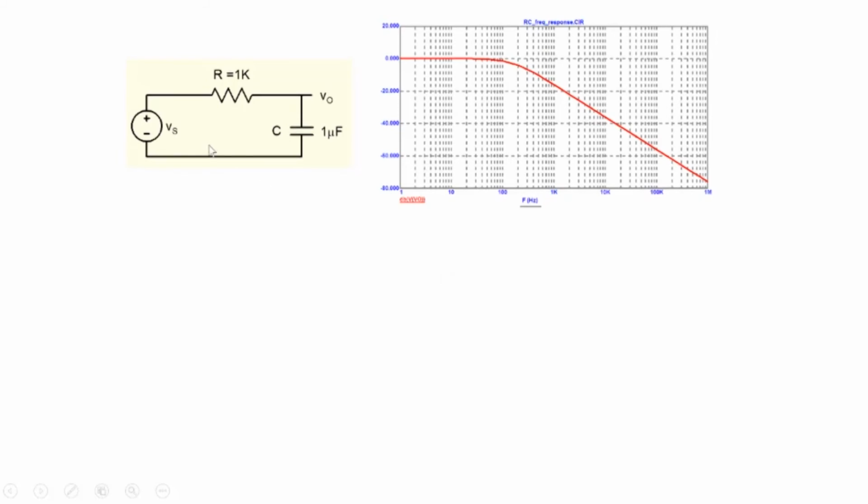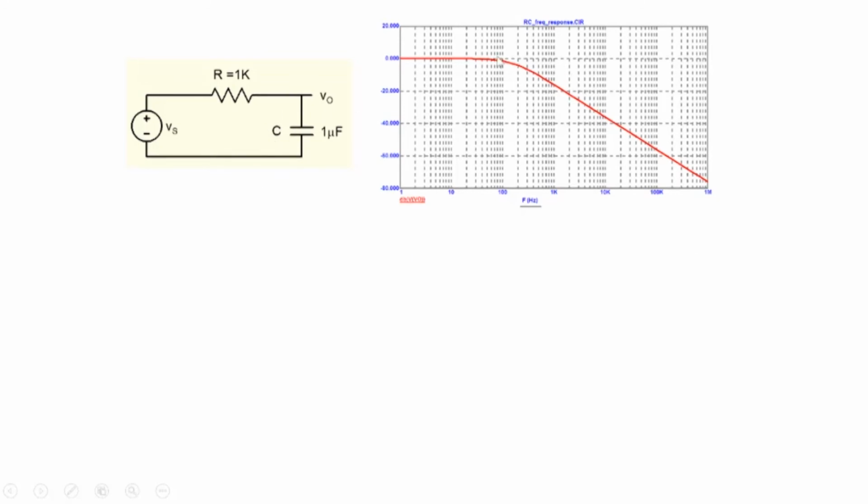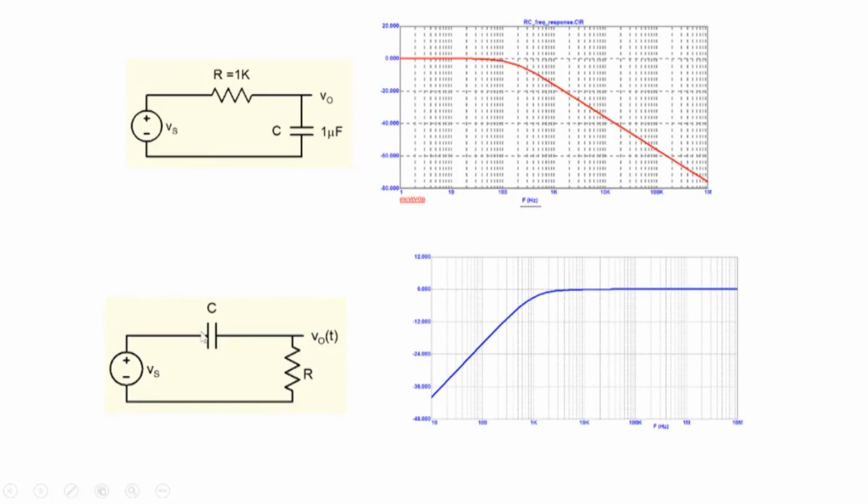As an example, this RC circuit that you see here, this R and C, you can calculate the transfer function. It has this particular form. When you have an R and a C here, it acts as a low pass filter. When you put a C here and an R here and you take the output across the resistor, then it acts like a high pass filter. By the way, before we do that, how do we quickly tell whether a filter is high pass or low pass?